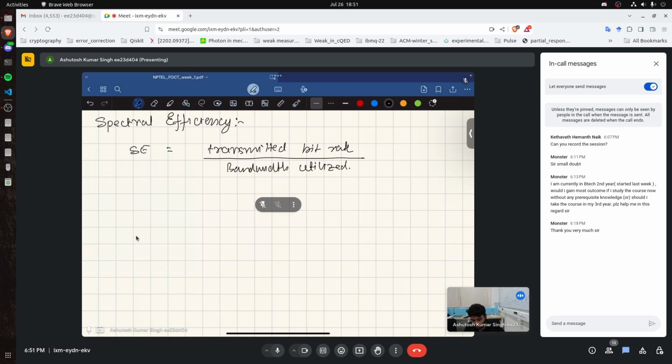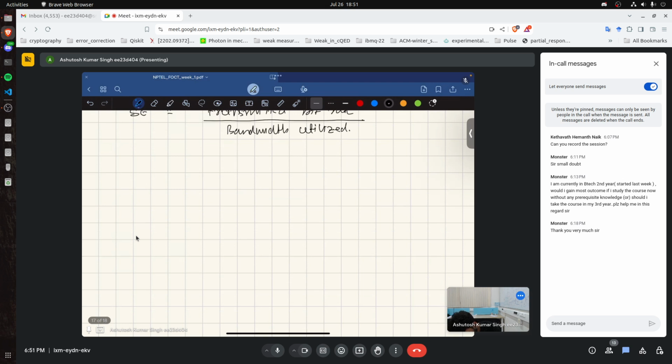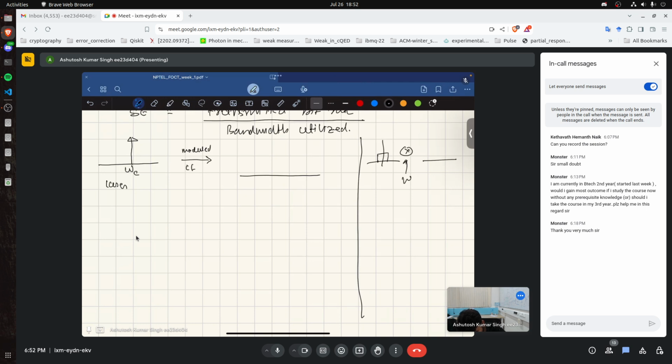So if I have a laser, let's say I had some initial laser here at frequency omega carrier, omega c. This is my laser frequency. I modulated it. By modulating, the narrow line width of the laser broadens because I am taking my baseband signal, and after modulation with frequency omega, you have shifted it to a different part.